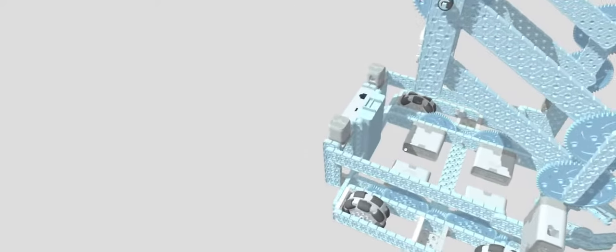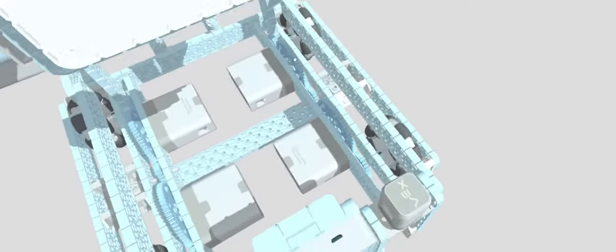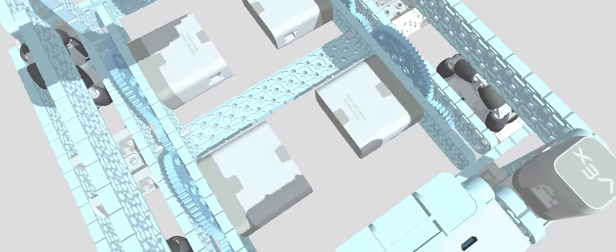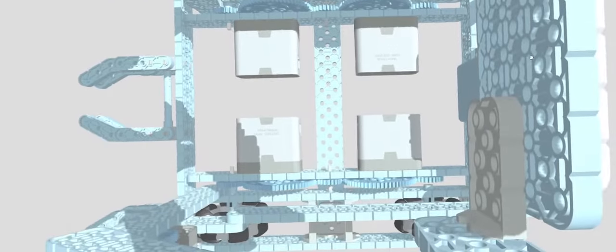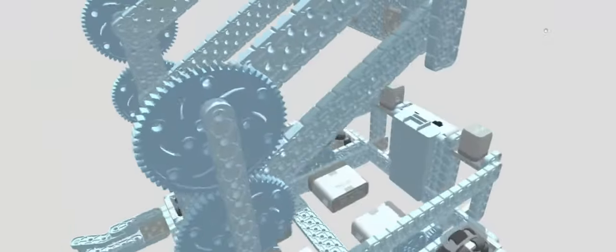You have a 4-motor drive base. In my opinion, I don't think 4 motors is really needed. I think we saw a lot of 4-motor bases today. I think 4-motor drive was only needed last year because you had to get around an empty field a lot. But this year there's a lot of scoring objects, really similar to Full Volume. And in Full Volume, not a lot of teams actually used a 4-motor drivetrain at Worlds. So I think 2-motor drivetrain will remain kind of the meta throughout the season, since you could do a lot more.